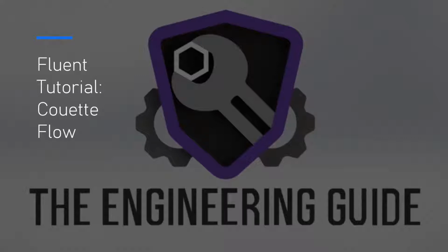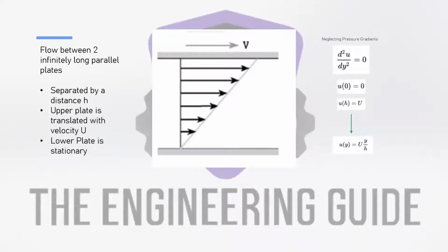Today we're back in Fluent simulating Couette Flow, and I'll show you how to do it. So just a quick overview of Couette Flow before we start. Couette Flow is a shear-driven fluid motion that describes the flow between two infinitely long parallel plates that are separated by some small distance h, where the upper plate is moving with some velocity u, and the lower plate is stationary, meaning that the velocity is 0.